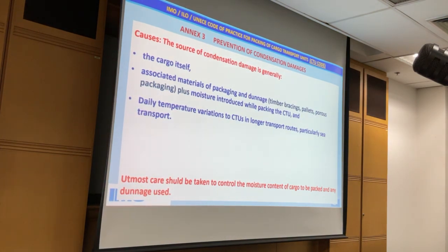Causes are generally the cargo itself. The cargo itself may have high humidity, while during packing in some cold climate or warm climate, depending on the destination, it will end up either in container sweat or cargo sweat. Associated materials of packaging and dunnage may have high moisture.